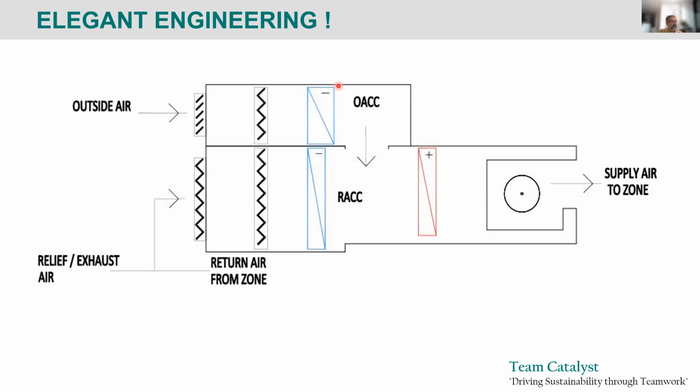And we had a dual coil system. So we have a fat coil, many rows. It takes the outside air. So the hottest air meets the coldest water, so you have the most efficient heat transfer. You drip all the moisture out at that point. And then that cold air you put into the mixing box. And there's a trim return air cooling coil. And there's a trim heating coil in case the air gets too cold. Okay. That's kind of like the magic box, if you wish.